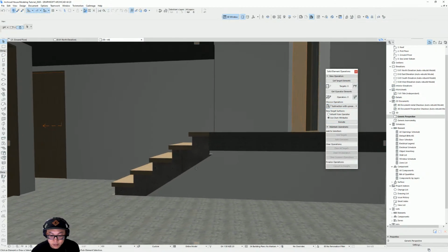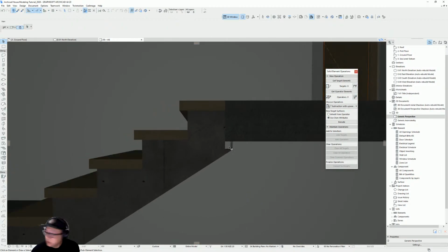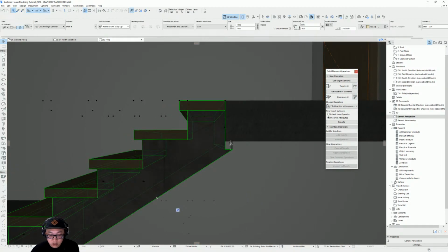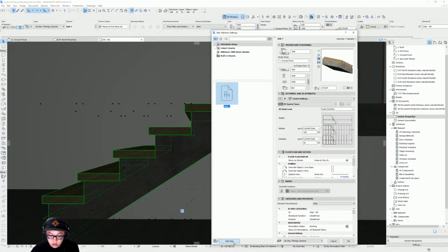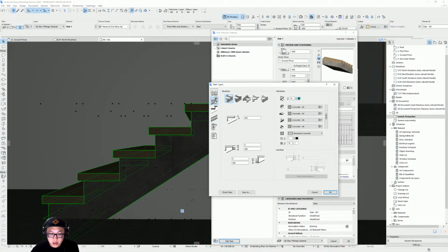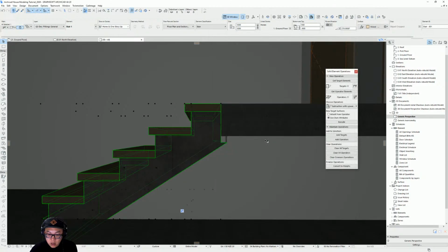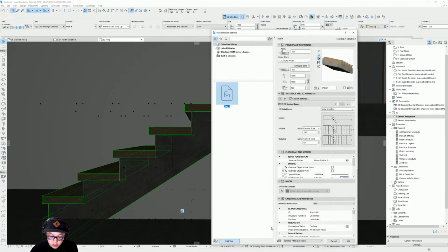Wow. Okay, these little things here, that's because of the setting there. I think I need to add the staircase. I think it's this one here. I need it to match the width of that slab, and I think it's like a 250, and it was set up at 300, so I just need to change it to 250.